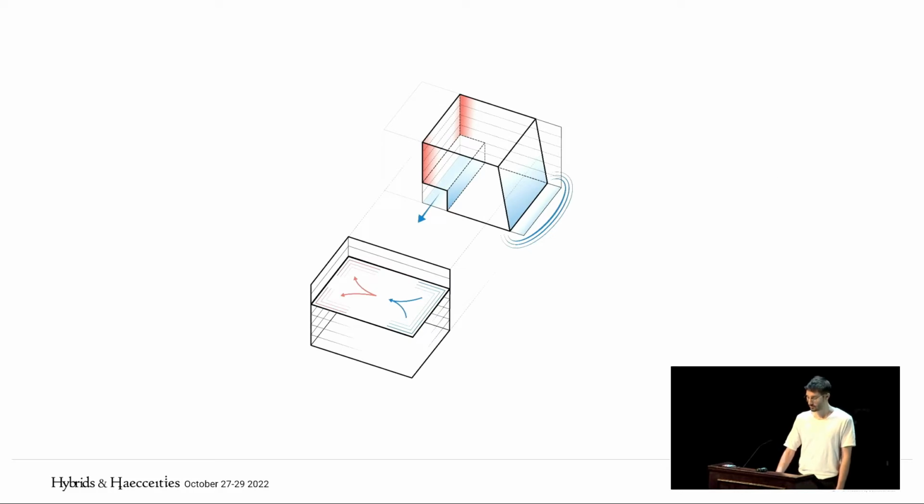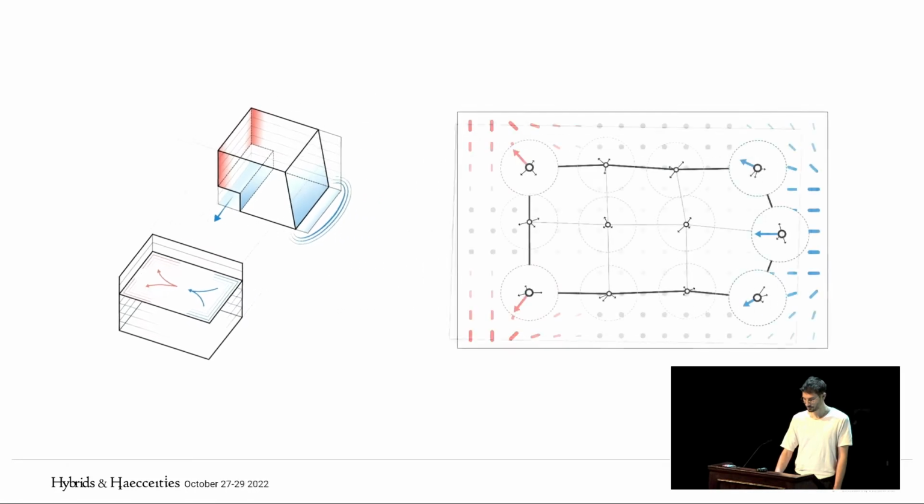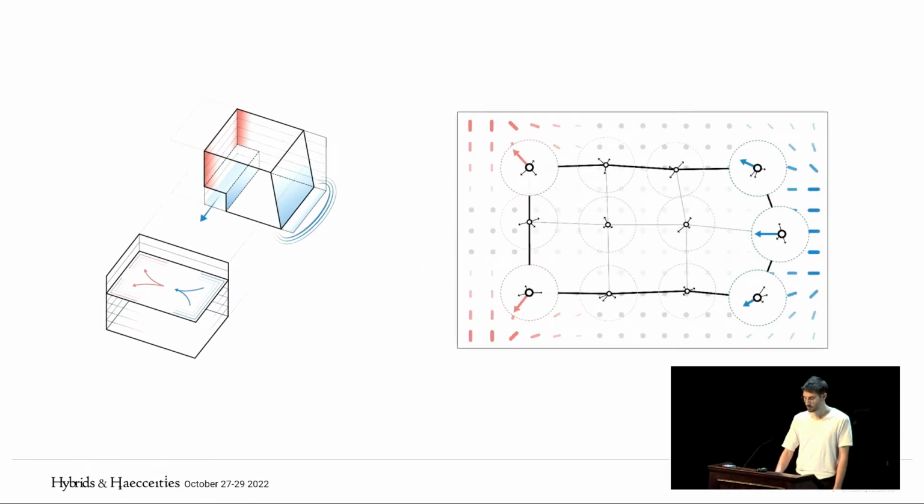Our approach to informing agents about massing or site-related objectives is to encode information in the Euclidean agent environment. To do so, designers define areas within the three-dimensional instance of the environment that are to be avoided or populated by agents. In a second step, this information is mapped to the corresponding two-dimensional instance of the environment and translated to a vector field that attracts and repulses agents.